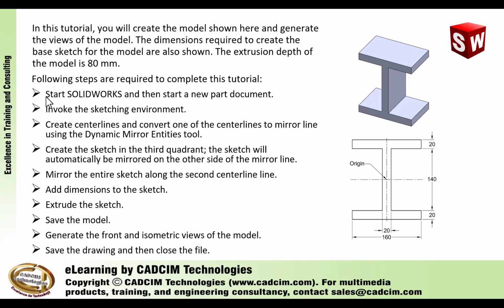First, you will start the SOLIDWORKS application and then start a new part document. Then you will invoke the sketching environment. After that, you will create center lines and then convert one of the center lines to a mirror line using the Dynamic Mirror Entities tool. Next, you will create the sketch in the third quadrant. The sketch will automatically be mirrored on the other side of the mirror line.